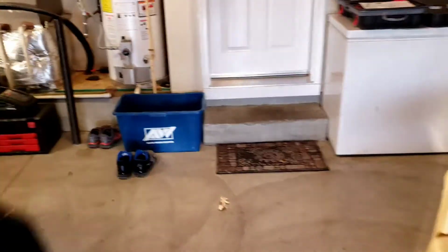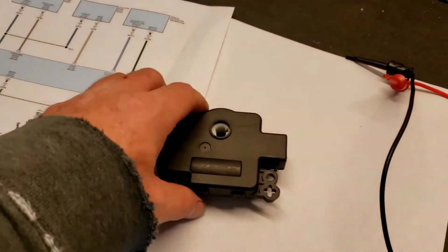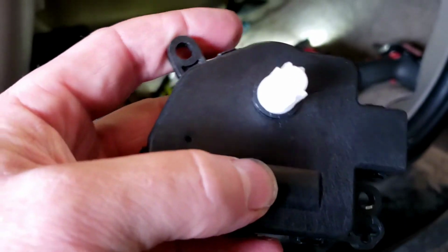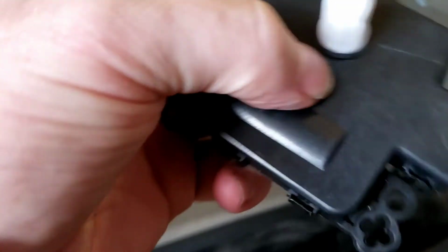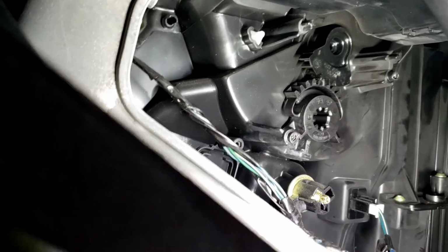So I already took the old one off. I got it on the bench up here, but that's the old one. And then I'll show you here, I got the new one here. If you look, there's an alignment mark from the factory when they build these. You gotta get it blended. You can see the arrow pointing to that bigger open spot there. That's lined up, but you can see the gears, and you gotta make sure that's hooked. You can only put it in one way. It's easy. I'm gonna go ahead and put this in, and we'll go from there.